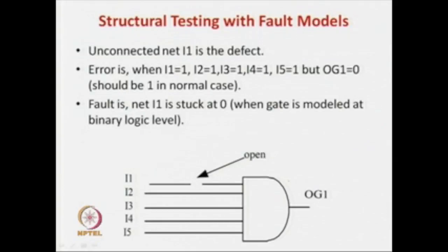So, this is an AND gate. We have already seen that a NAND gate is so complex, at the transistor level it can be faulty, at the layout level it can be faulty, so a lot of faults can be there. For example, let us assume that this is a stuck open fault. This line is somehow cut, this input is somehow cut. This is actually called the defect: the layout is not proper, the metal should be like this, but somehow there is an opening.